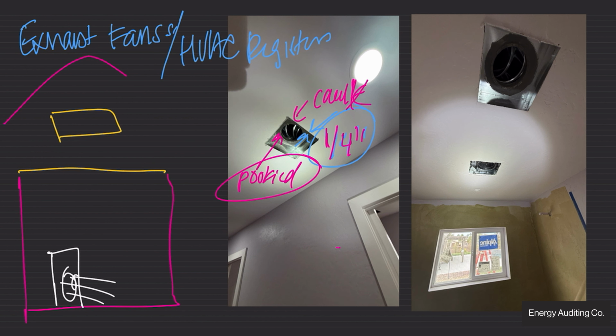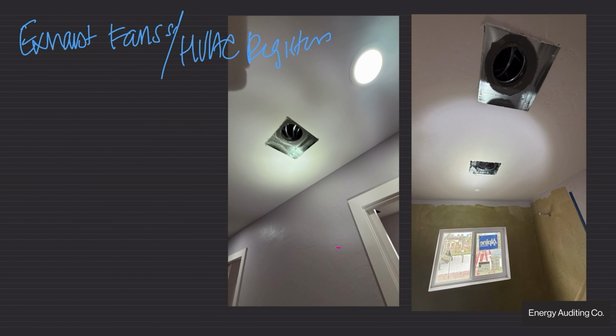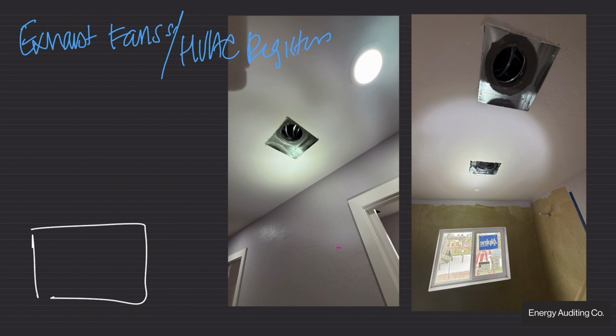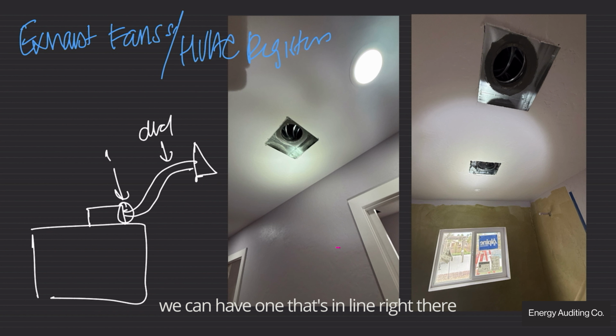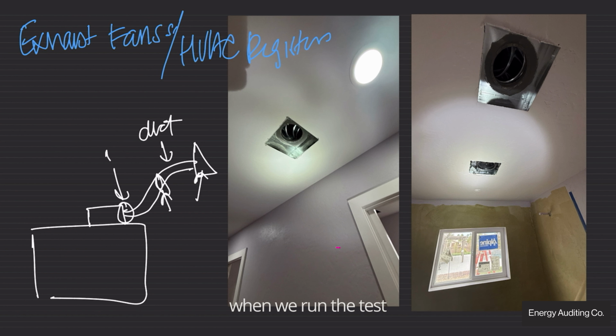Another thing, as it primarily relates to exhaust fans, is that if your exhaust fan, say here's a bathroom, right? If your exhaust fan, let's say here's its exhaust duct, right? If this guy doesn't have a damper, which is like a door, right, that just falls open and shut, it can have one right here, location 1. We can have one that's inline right there, or we can have a third one that is right here at the end. If we don't have a damper at either of those locations, when we run the test, air will just get sucked in right through this guy.